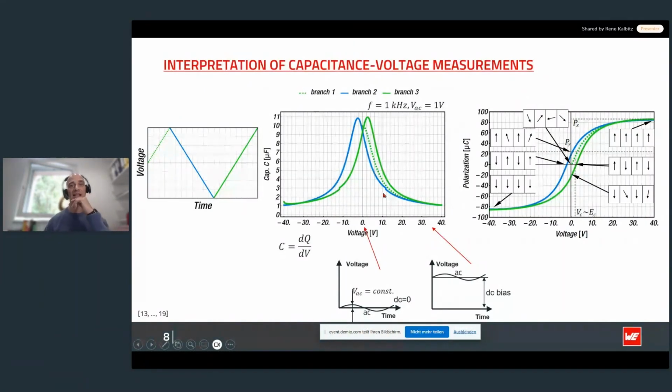When the applied external field E, which is proportional to the applied voltage, has aligned the majority of domains, the dipoles remain in this position, even without the external field. The collective alignment creates an internal stabilizing coercive field.